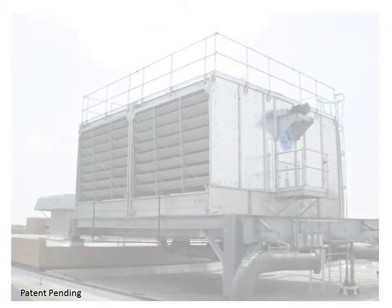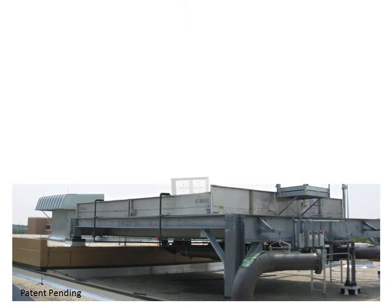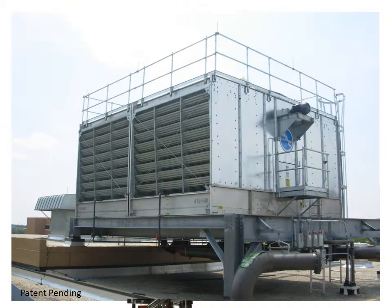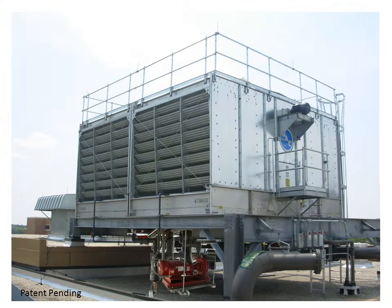You're looking at a standard cooling tower. The appropriately sized directional filtration is placed in the cooling tower basin. This changes the direction of the flow, but cannot impede the flow volume. This filter is also self-cleaning. A tower basin sweeping system is installed. This keeps the suspended solids off the basin bottom. These solids are then filtered and removed from the system.